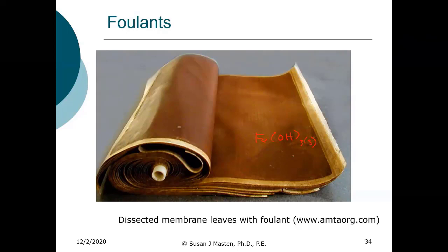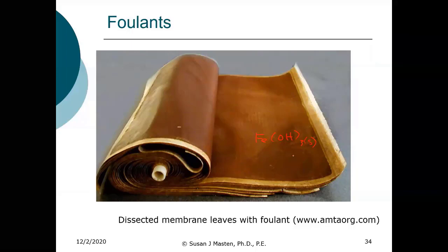And you can probably imagine getting flow through that membrane is extremely difficult. About 20 years ago, when membrane filters were put in Chelsea, they didn't put in an iron treatment system. Within a few weeks, the membranes all looked like this. They then had to go back in and retrofit the plant in order to remove iron prior to filtration to prevent this.